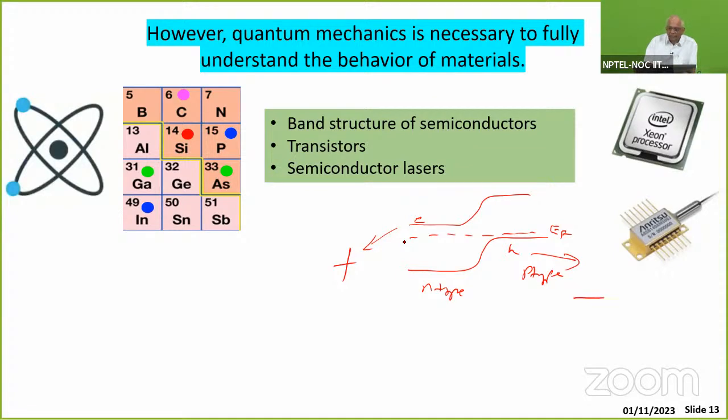Barrier height. Yes, the barrier height is important, but electrons don't go to this side, they have to go to the contact. The holes don't go here, but go to the contact. This barrier, that's what it does. It's a barrier for electrons. Similarly, there's a barrier for holes. The electrons have to diffuse. So therefore, the characteristic length is the diffusion length.